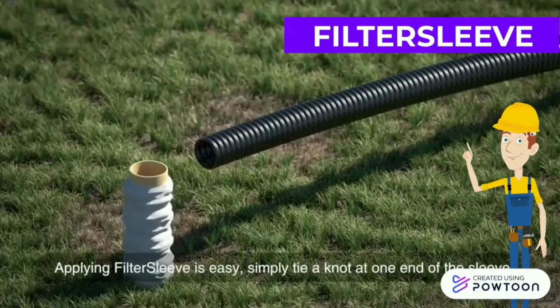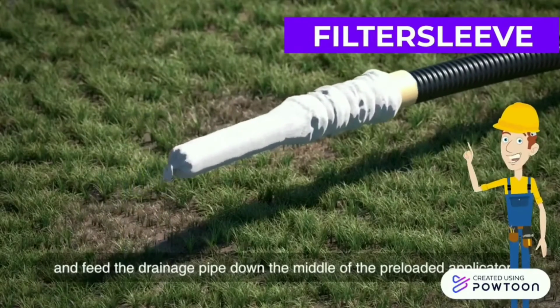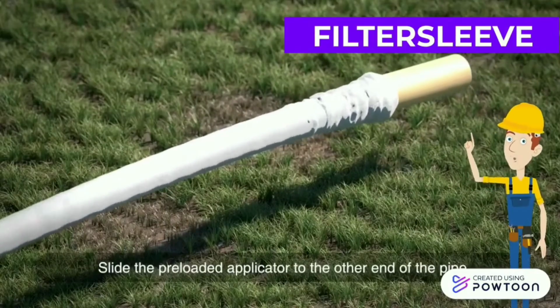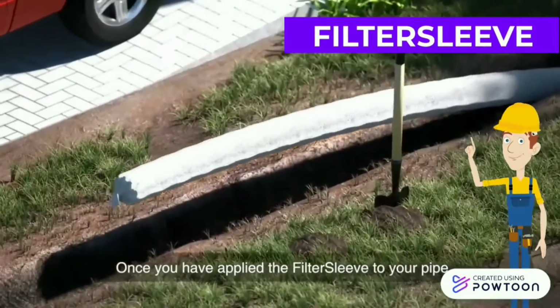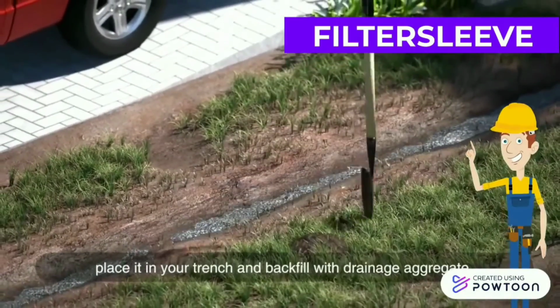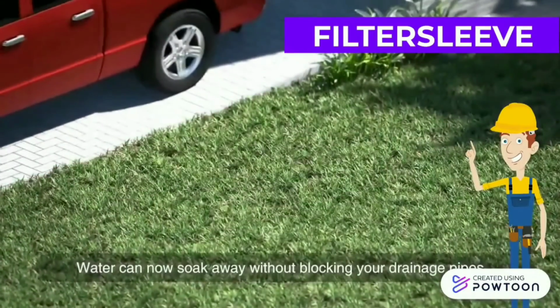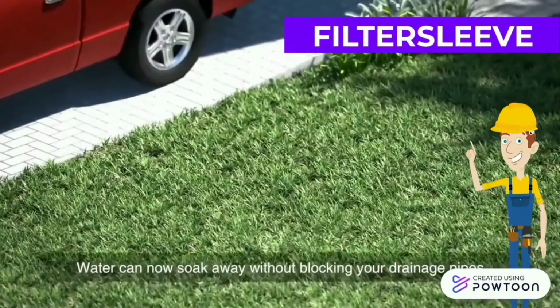Applying a filter sleeve is easy. Simply tie a knot at one end of the sleeve and fit the drainage pipe down the middle of the preloaded applicator. Once you have applied the filter sleeve to your pipe, place it in your trench and backfill with drainage aggregate. Cover with topsoil and plant grass seed on the exposed areas. Water can now soak away without blocking your drainage pipes.